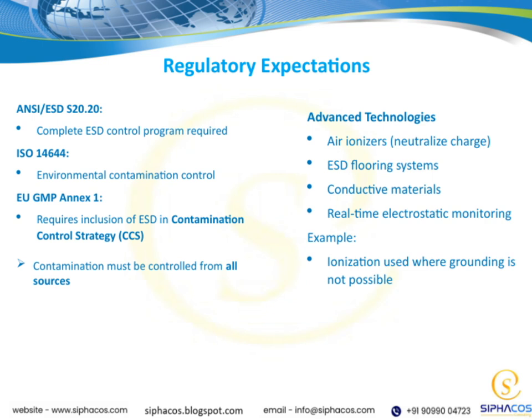Moving on to regulatory expectations, it's important to understand that standards like ANSI ESD S20.20 require a comprehensive ESD control program. This isn't just about having some measures in place. It involves a complete, well-managed approach. ISO 14644 emphasizes the importance of controlling environmental contamination, which directly ties into our static control strategies.